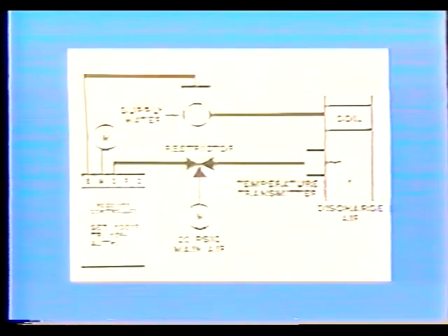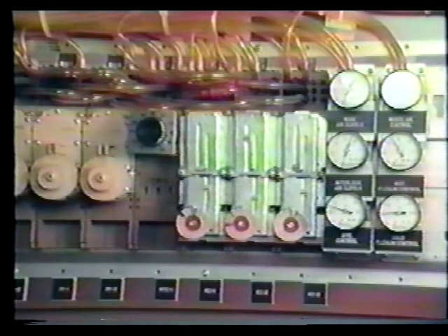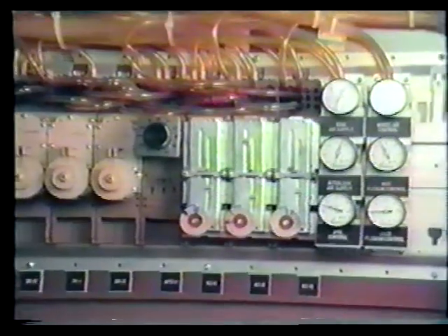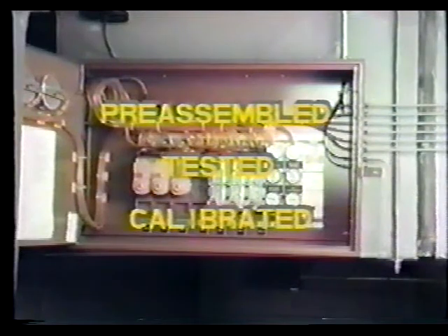At this central location, the signal being transmitted from the transmitter is piped to a receiver controller, or controllers, which then provide the controlling signals for the system. The centralization of the control functions allows the control devices such as logic relays and other necessary hardware to be conveniently located for calibration and service. This also allows control panels to be pre-assembled, tested, and calibrated in a panel shop so they are ready for on-site installation and hookup prior to the startup of the building.